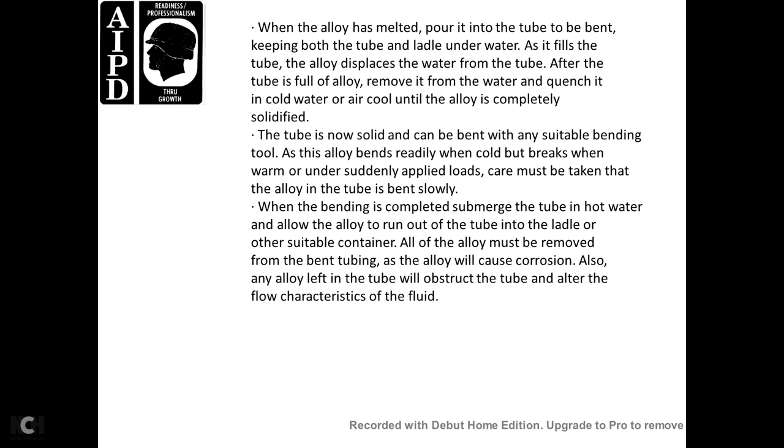The tube is now solid and can be bent with a suitable bending tool. This alloy bends readily when cooled, but it breaks when warm and under suddenly applied loads. Care must be taken to bend the alloy-filled tube slowly.